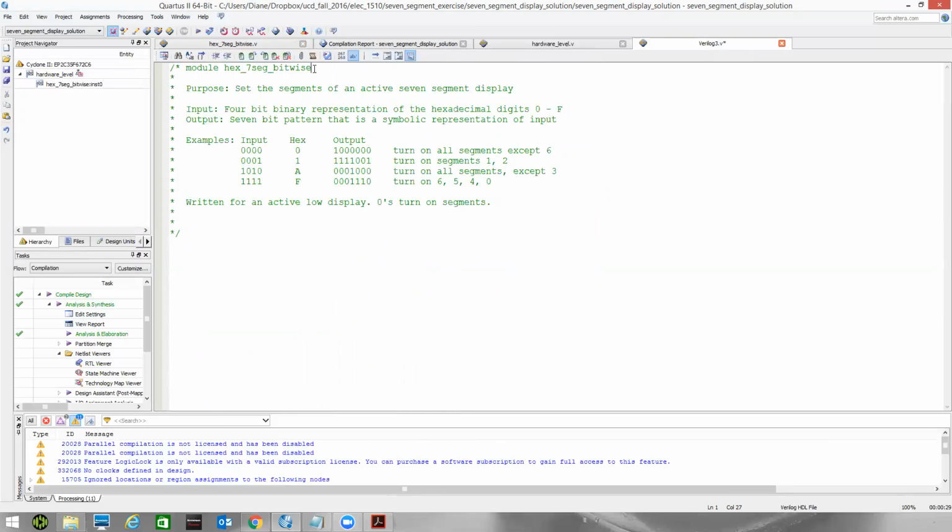All right. So I won't call this hex to 7-segment bitwise. Maybe I'll call this case, for case statements. All right, same behavior. So we're going to start with the keyword module, x7seg, calling it case, because I'm going to use case statements. Right now, my input, over our truth table, we were calling this A, B, C, and D. All right, and then we had our output wire of our 7 segments.